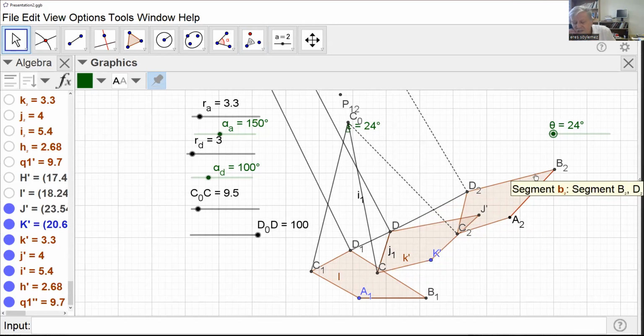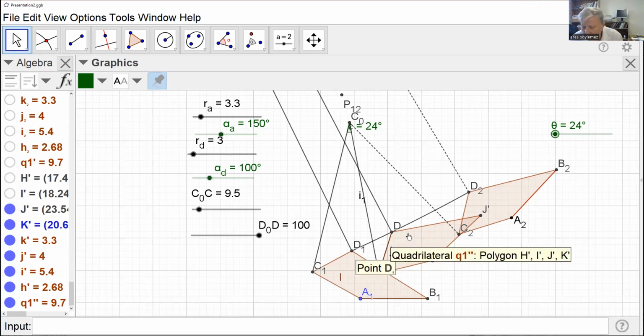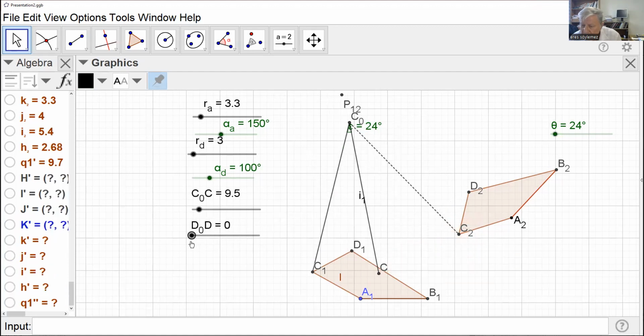There's no rotation. It is almost a straight line. If D0 is selected at infinity, with D1, D2, I can attach a slider to it, and I can obtain a slider crank mechanism. C0, C1 is the driving link, the crank. I will have a sliding joint at D1. I can also attach a sliding joint at C1 and use D1, D0 as a crank. That's also possible.